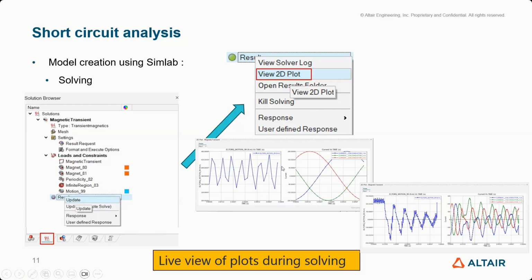As you can see from this picture, if you see, for example, some wrong behavior or some wrong shape of your curves, in my case, I displayed the current and the torque. I can check both curves and see, for example, if I really manage to reach the maximum current that I created before or not. From this curve, I can see, oh, my simulation is correct.